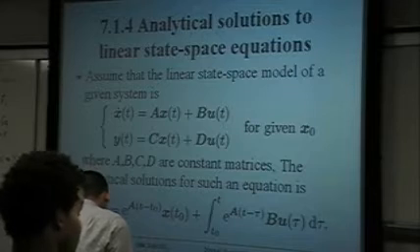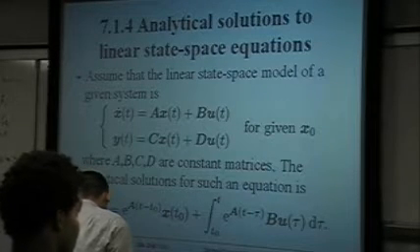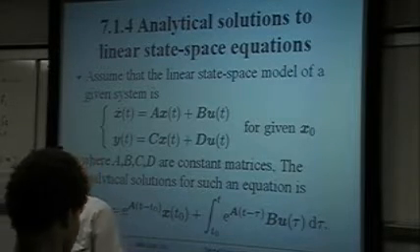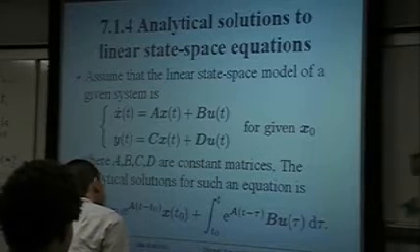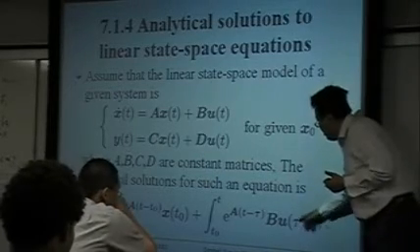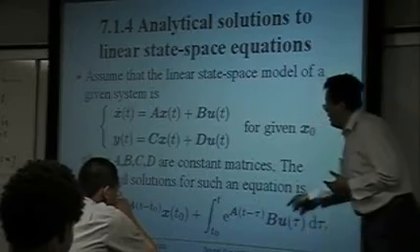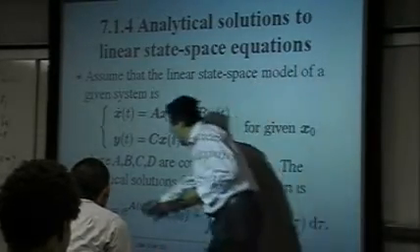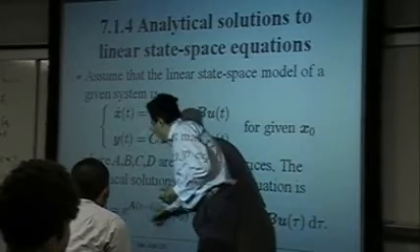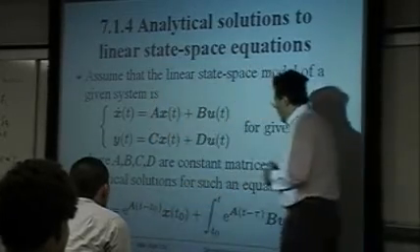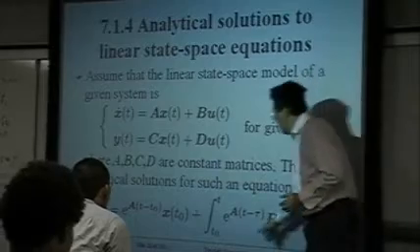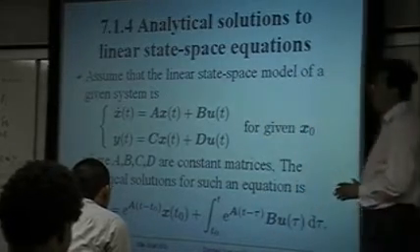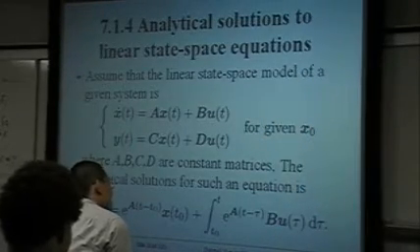And for linear state space equations, since the original analytical solution can be described in this way, we can easily use Matlab commands. For instance, expm to calculate this part, the state transition matrix, and then use int to perform integration. So we can also solve the problem in that way.